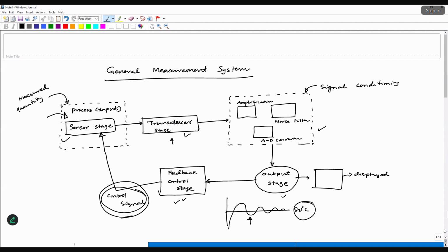Noise is all extraneous effect that you do not have any control over. It comes from experience how you differentiate noise from data. So you need to do the appropriate thresholding to throw away noise without influencing data. And in fact, your analog to digital conversion also comes under signal conditioning. Okay. Thank you, sir.